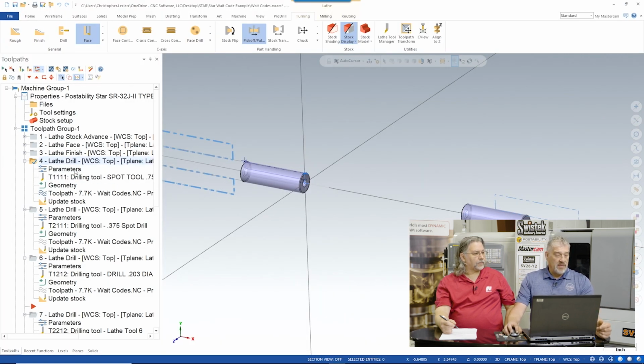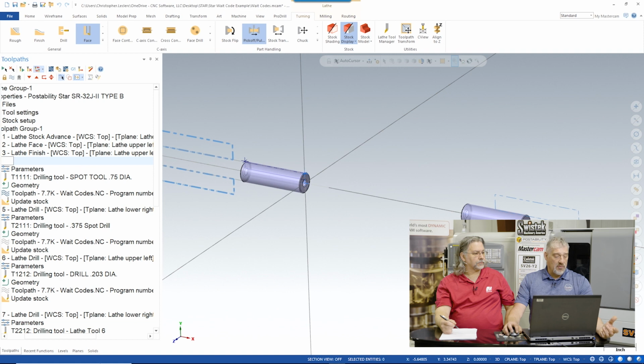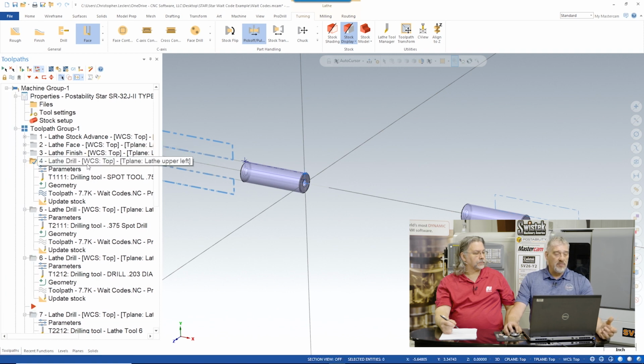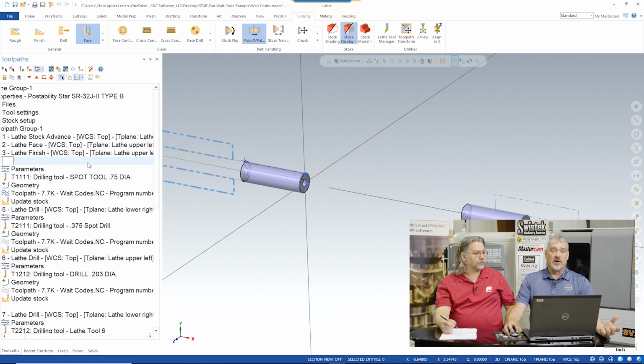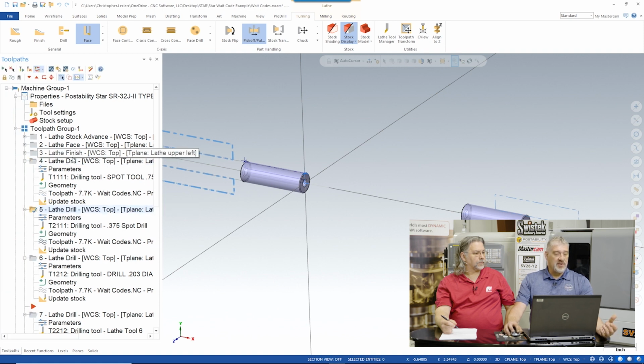What I do is I'll write my operations back to back. So if I know I'm drilling on the main, I'll write the main one first, and then immediately I'll write the tool path to do on the sub, so they're tied together so I don't get confused if it's five operations down. Just keep them tied together to make things simple.